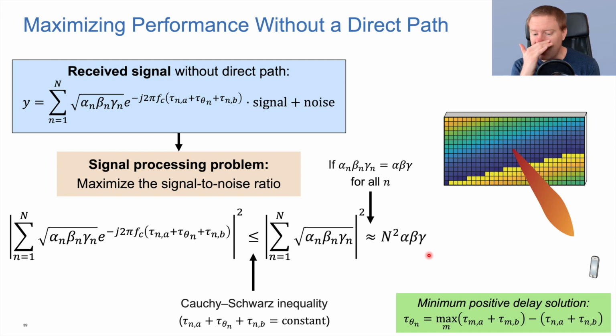So this is an interesting thing that happens, that the signal-to-noise ratio is increasing in not a linear manner, but a quadratic manner with the number of elements. So the motivation behind that, or the explanation, is that you have a surface area that is growing with number of elements, we're capturing more energy, and that gives us one linear increase with number of elements. And then as the surface gets larger, we also get a smaller beam width. We're focusing the energy more and more, and that gives us another factor n as our beam forming or array gain.